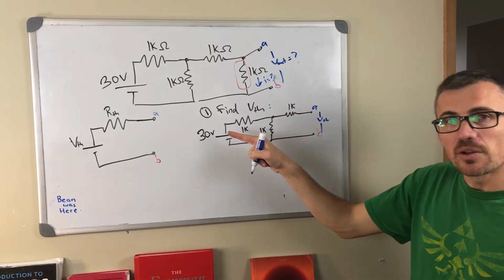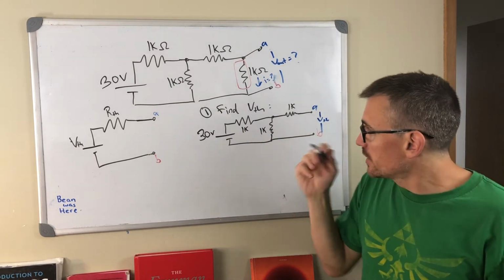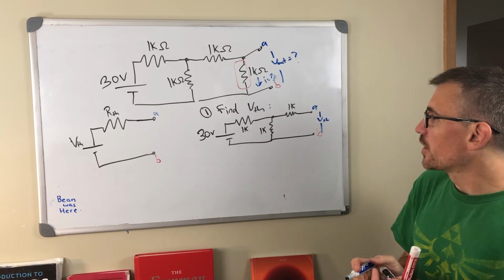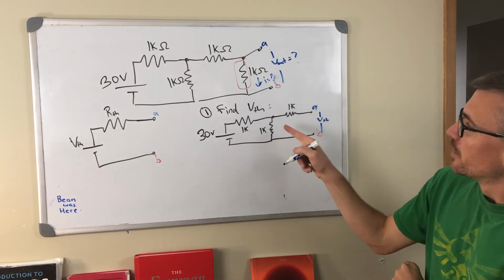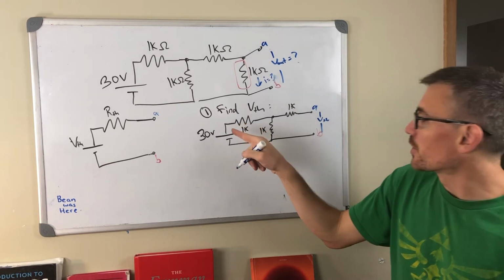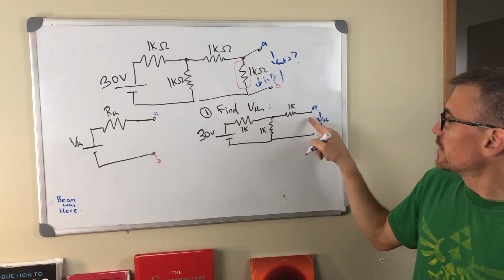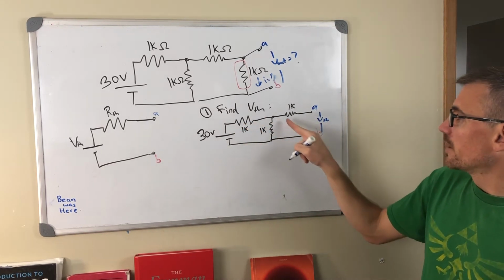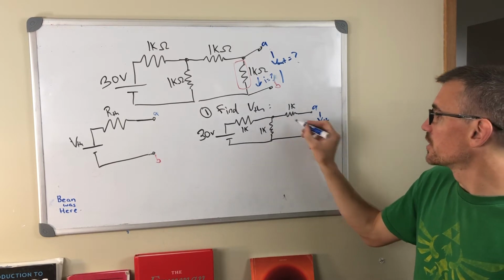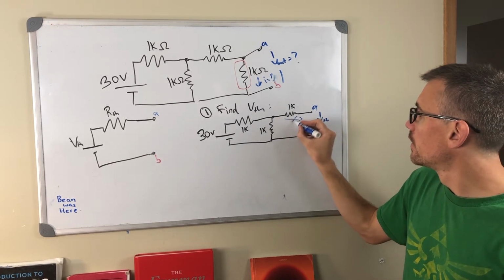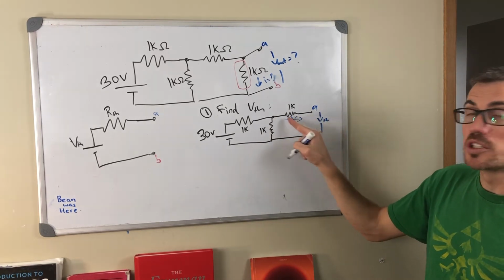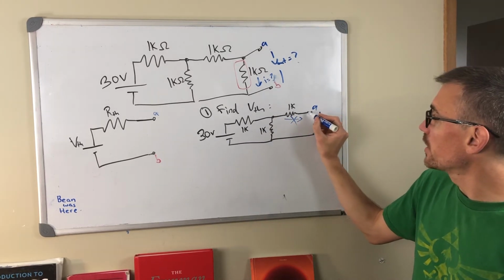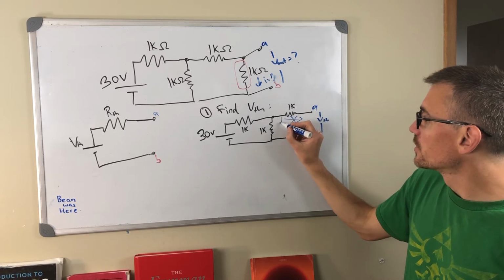So where is the current flowing in this circuit? And this is always the case with calculating V Thevenin and R Thevenin. You draw it and you stare at it for a second, and usually something pops out. So we can see here this is actually a much simpler circuit than it looks like at first. Because this is an open circuit on this side, how much current can flow across this resistor? None, right? There's no current flowing across it, and that means no voltage is dropped across it. So it's the same potential here as here as here. This is also V Thevenin.